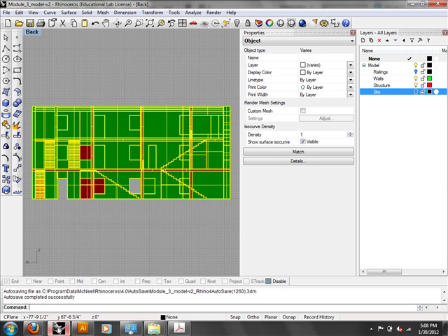Nick? It's going to be the same thing, but we were talking in class, if we put a clipping plane, it still sees the other stuff. Is there a way you can tell it to only see? The way Make2D works, guys, is like if you had two 3D pieces of geometry and you wanted to make a 2D jig to cut that shape out, that's what it's for. It's a method of projecting that geometry. The way we're using it for a camera view is not what it's meant to do. So there's no use of the clipping plane because that's not the original use of the tool. You have to do a lot of work with this stuff. It doesn't just pop out.